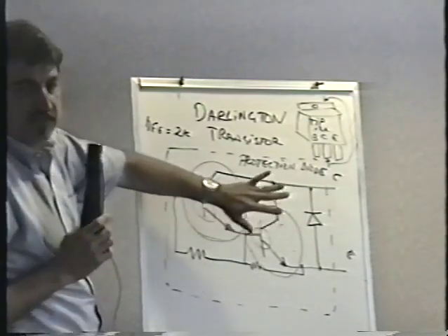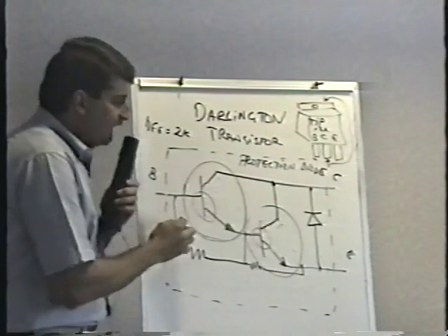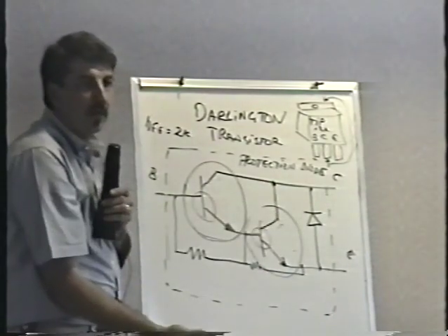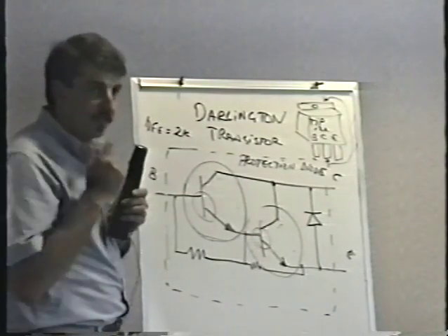And the fact of the matter is, the reason I'm not worried about this is, when these transistors fail in a pinball machine, they always dead short collector to emitter. So it's really easy to find bad transistors. I'll talk to you more about that on Saturday.